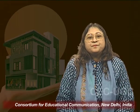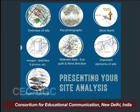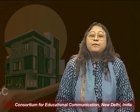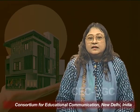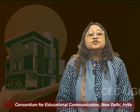site analysis projects. While going and presenting your site analysis, make sure you have an overview of the site and key photographs. Always mark north because it will straight away impact the orientation, sun path and wind direction. The relevant data available in terms of sun path and wind direction, important elements of the site and overlay of the drawings are important while you are presenting your site analysis. This is how a typical site analysis sheet looks, which has all the important aspects and parameters of the site analysis.